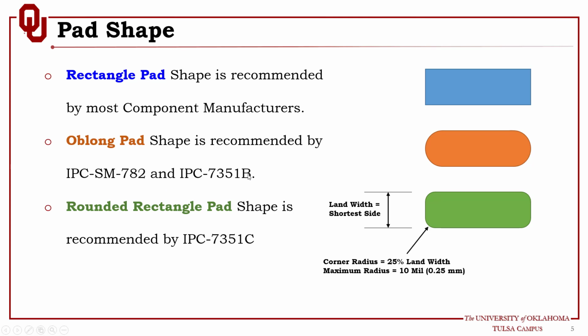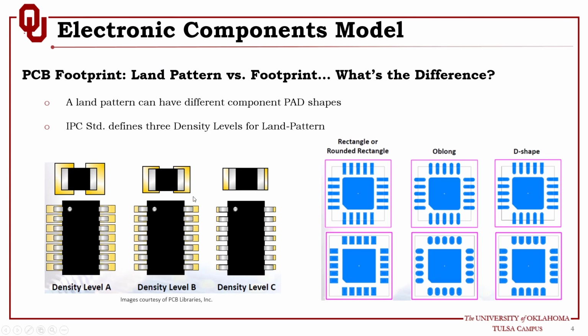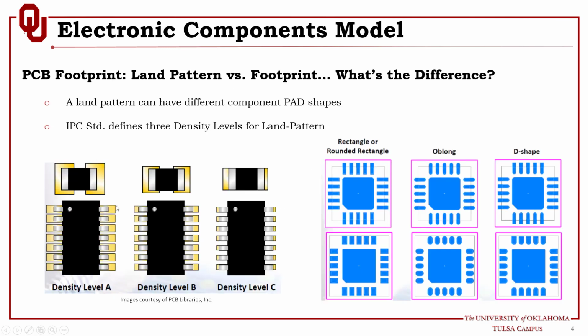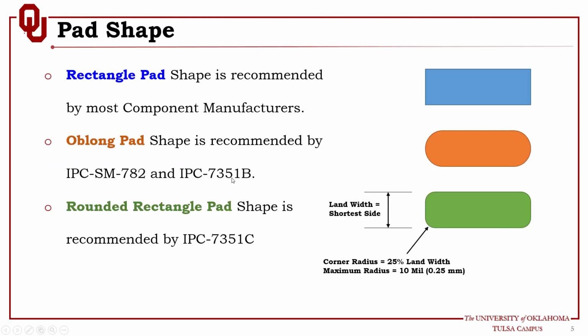IPC-SM-782 and IPC7351B. So that standard we were talking about in here, IPC7351C, is basically the latest version of the IPC7351B. So, in the C, the oblong pad is not recommended. It's only in the B.